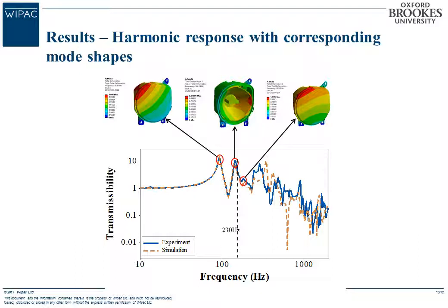The first mode shape shows that the whole assembly is under bending condition, rotating about the upper and lower left lamp mounting brackets. The second mode shape also shows that the assembly is under bending mode, moving along the lateral direction. For the third mode shape, there is a combination of tensile, compression and bending modes. The assembly is moving with respect to the longitudinal direction. The mode shapes clearly showed that we are dealing with a bending related problem.